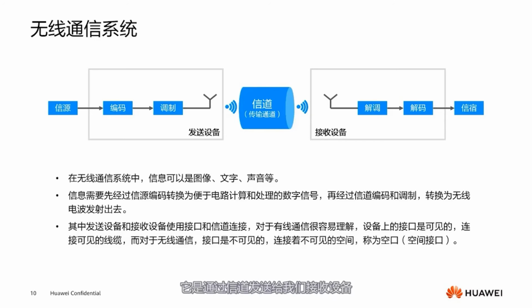What is a channel? We mentioned frequency earlier, like 2.4 GHz. This frequency range is quite large. Various frequency signals can go through it, like a road, say 20 meters wide. If you don't plan it, everyone will just wander, and the efficiency will be very low, so we need to divide it into lanes. Each person just stays in their own lane and won't stray into others. The channel is the same. For example, I number them 1, 2, 3, 4, 5, 6, 7. You can only walk in channel 1. This is now the concept of a channel. We divide the frequency into different channels.